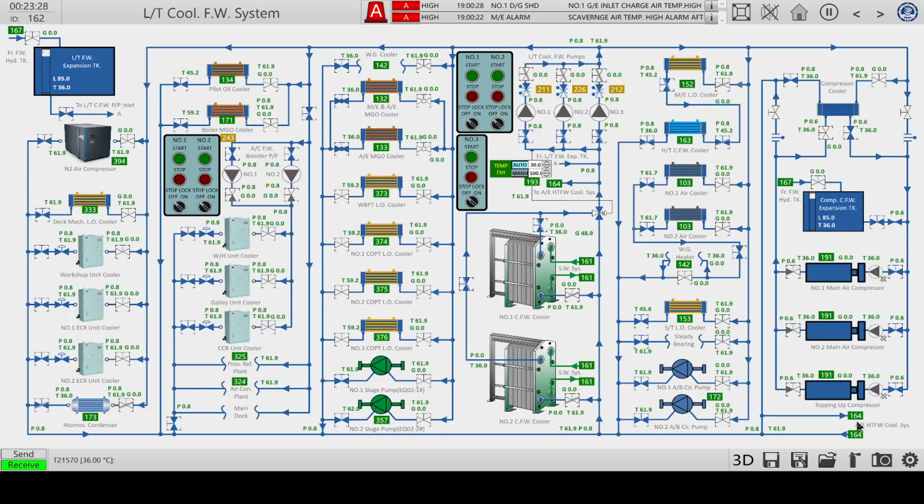So the freshwater cooling, the pages that we come through, these are the two. We're going to use the first freshwater cooler. This cools with the green seawater. So this will be this valve for the hot freshwater coming in, cooled coming out. And let's set up all three pumps and try to start the first one. We do have pressure and indeed flow, so that's okay. We have completed the circuit for the freshwater cooling.